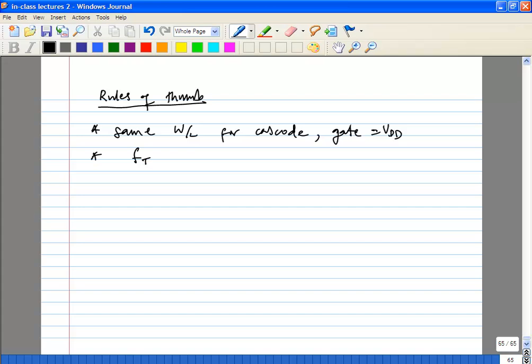And last week we saw you are going to choose W opt and power consumption, so you get some FT. It's a good rule of thumb, because we saw that at around 10 times f naught, for the power constraint optimized width, your noise figure is around 2 dB, 1.9 dB. So this is a good point to start. Try to start off with somewhere around 10 times f naught. If you're starting off with lower, you'll probably have much higher noise figure.